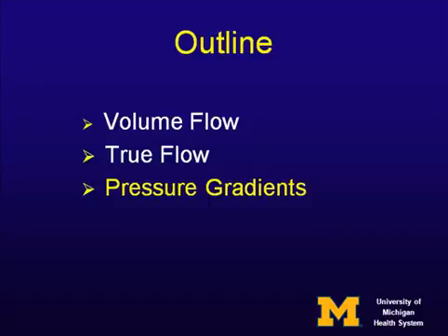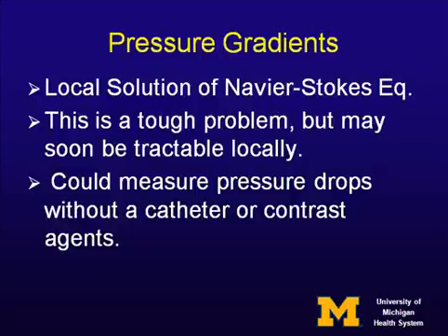But what I'm talking to you about now is not available, but the concepts are there. What you would be able to do with pressure gradients is solve to generate a local solution of what's called the Navier-Stokes equation. The Navier-Stokes equation is a very complicated nonlinear differential equation, which is sort of the bread and butter of fluid mechanics people. It basically describes the equation of motion of moving fluids. It's a very tough problem because it's nonlinear. But if you can sample fast enough and dense enough, it may be tractable locally.